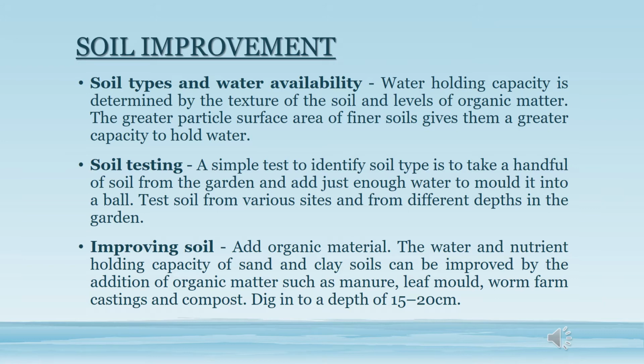Soil testing. A simple test to identify soil type is to take a handful of soil from your garden and add enough water to mold it into a ball. Test soil from various sites and from different depths in the garden.